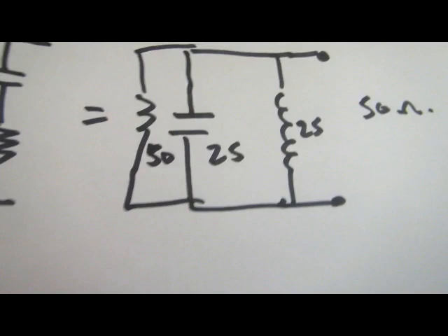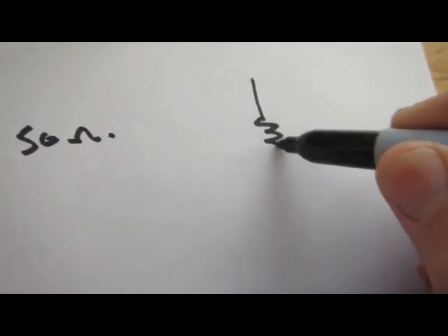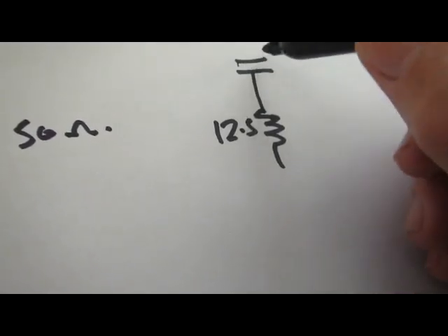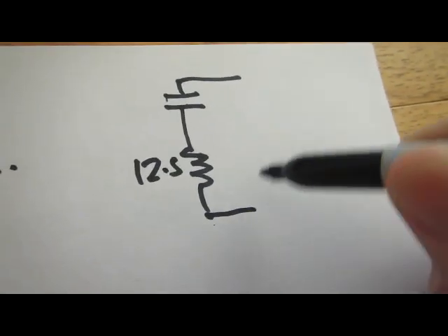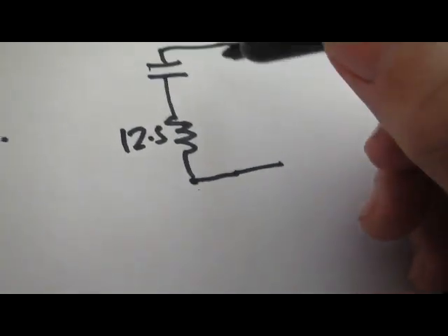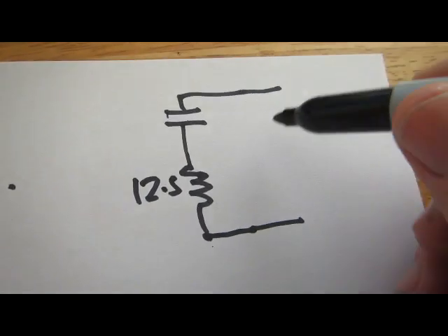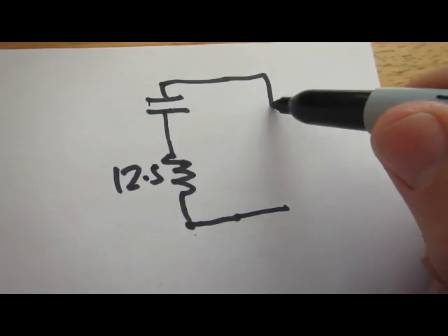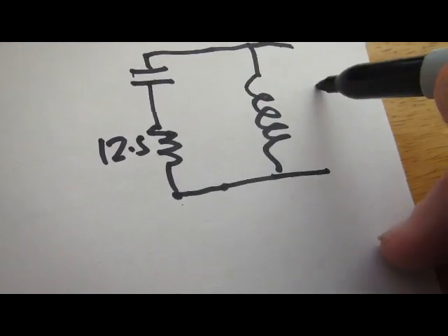That's it. So our final network, if I can just remind you: 12.5 was the antenna. We intentionally put 25 ohms of series capacitance, and then we found this has got a certain parallel combination which we liked, but to tune out the capacitance, which we purposely put in, we put an inductor. So that gives us 50.